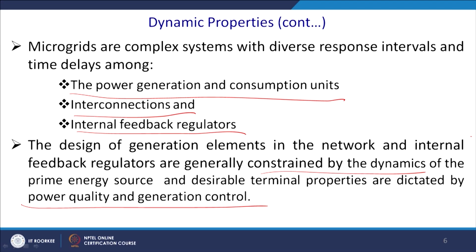While injecting power to the grid, you have to maintain the desired power quality, that is the THD has to be less than the value which allows you to export power to the grid, and you need to have a power factor close to unity, 0.95. Those constraints have to be put in place, and then only can you work with the grid.